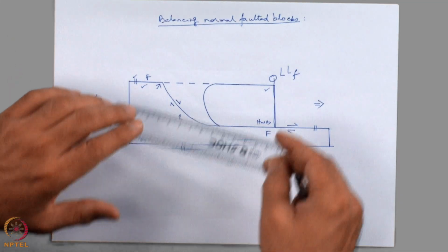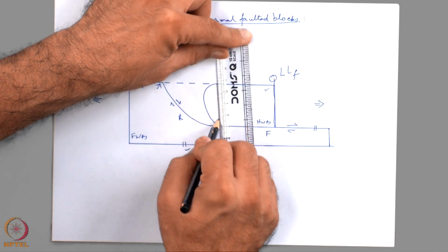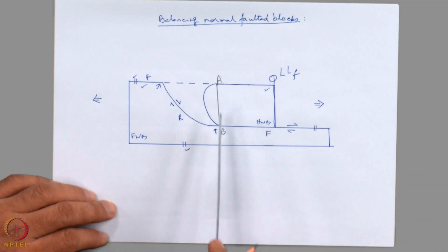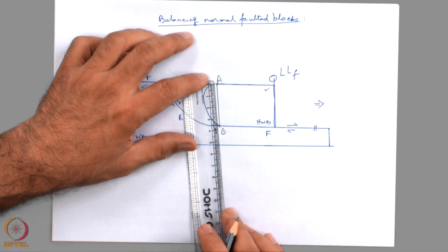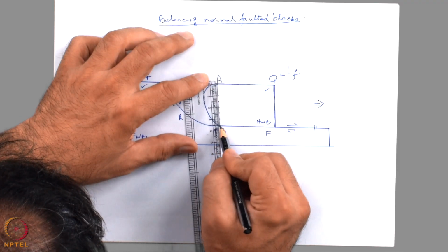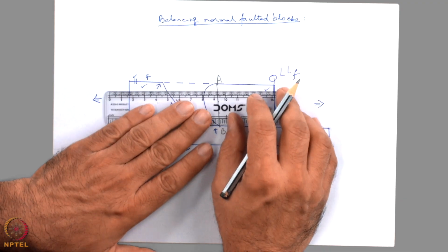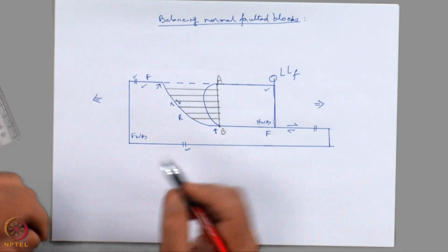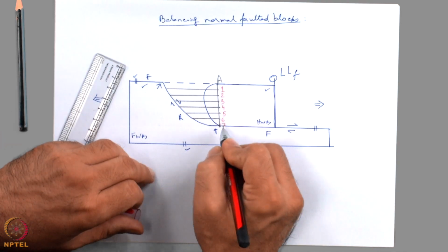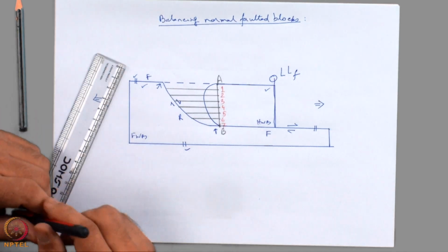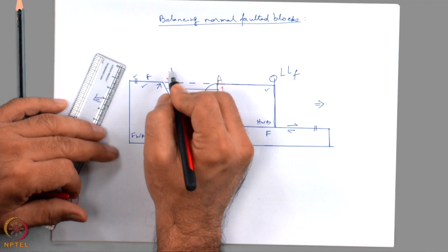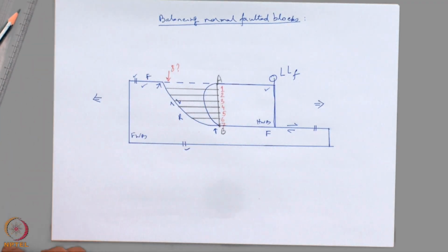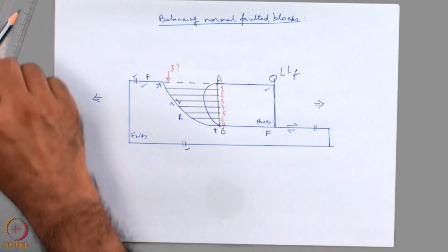To find out the area, I join these 2 points, say this is point A, that is point B. Now, the AB line is to be broken into smaller segments with 0.5 centimeter interval. Then I will drop normals on these points on the AB line. We have considered a total of 7 lines, this is a tiny line. Here a question comes, should I count this dashed line as number 8 line? And to avoid this question, one could have drawn or chosen the AB line in a different way.